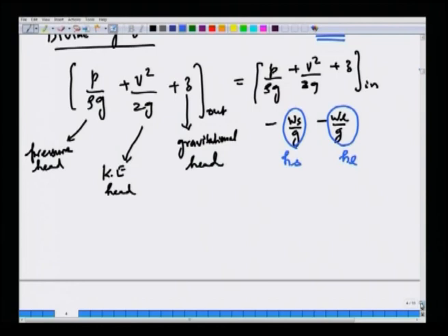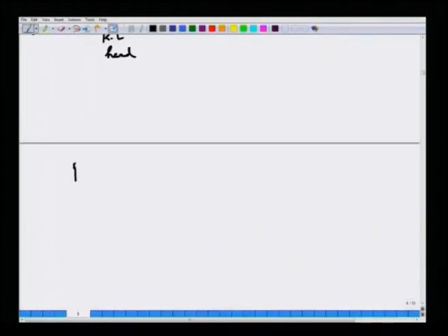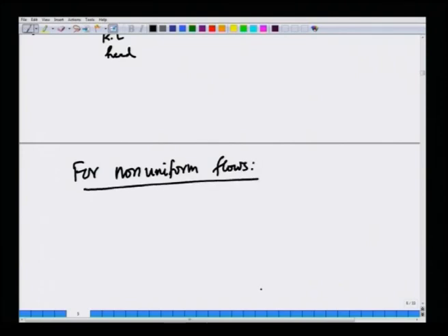As we told in the last lecture, for non-uniform flows, where the velocities are a function of the cross sectional area, just as we introduced the momentum correction factor in the last lecture, for the flux terms in the energy balance you may have to carry out this integral. If you recall, you have a term of the type rho half v squared v dot n dA over the control surface.